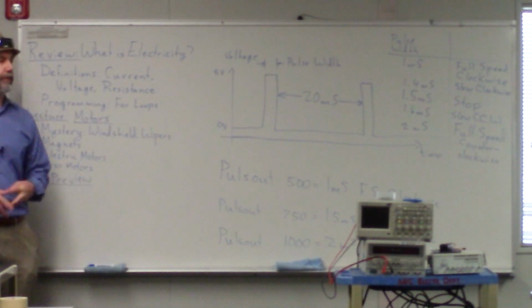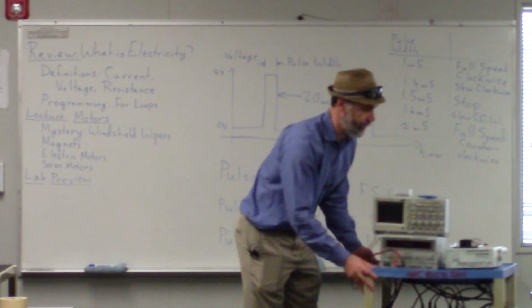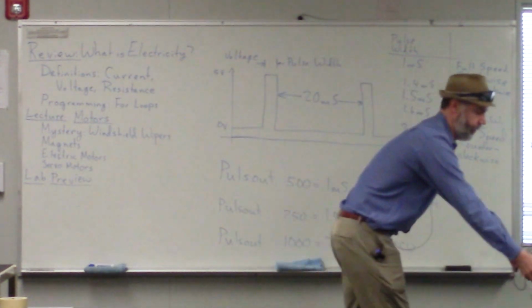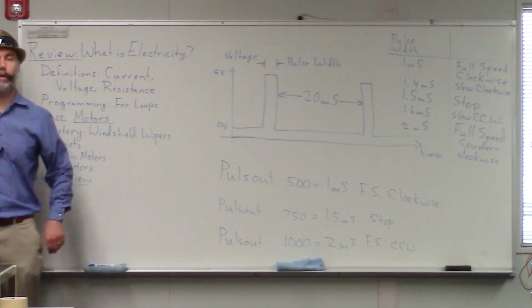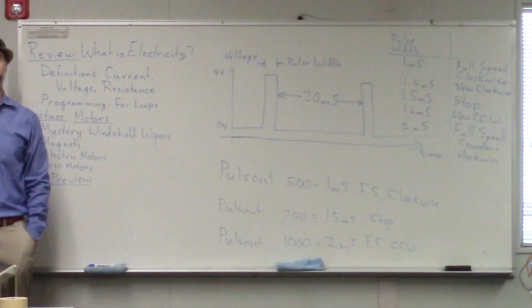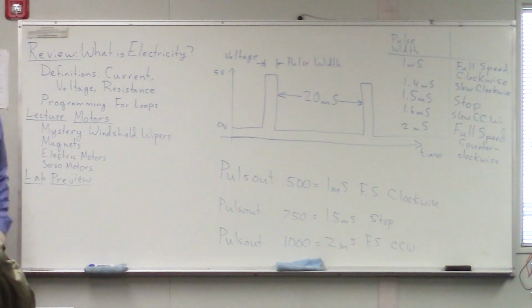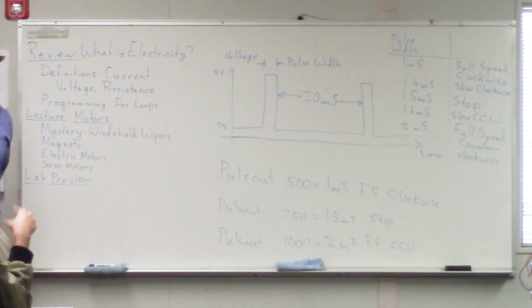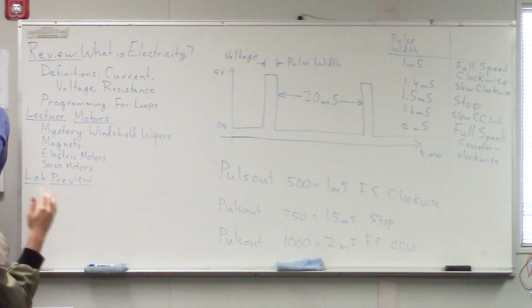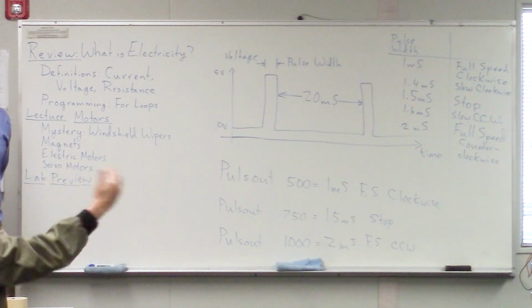So are there any questions about that? Let me get this cart out of the way so it's easier to see. So any questions about that? Yeah. So if we apply the voltage, 5 volts for 1 millisecond, it turns full speed. And if we increase the time to 1.4, so 5 volts will last for 1.4. Right.